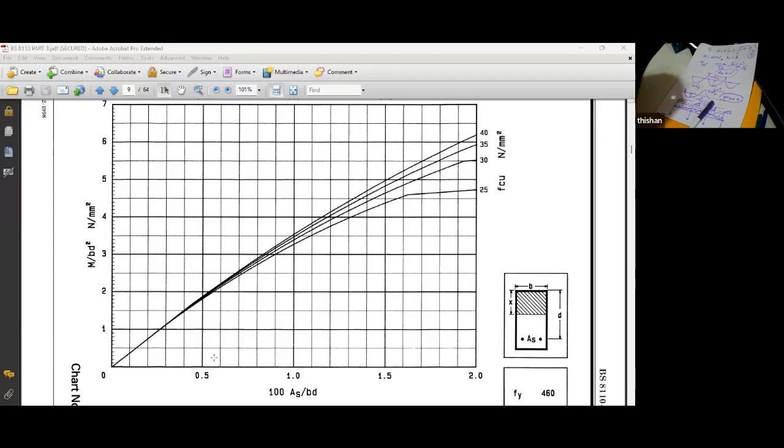Why? You can't put a vibrator. Why? The width is so small. So select a wide width for the beam. What is the main advantage? Shear capacity is high when the beam is wide. Very easy to do the construction. No honeycombs, no leaks, because it has plenty of space. We can vibrate it properly. We can pour the concrete from above because reinforcement has sufficient depth. And the structure is also very strong because it has high shear capacity.